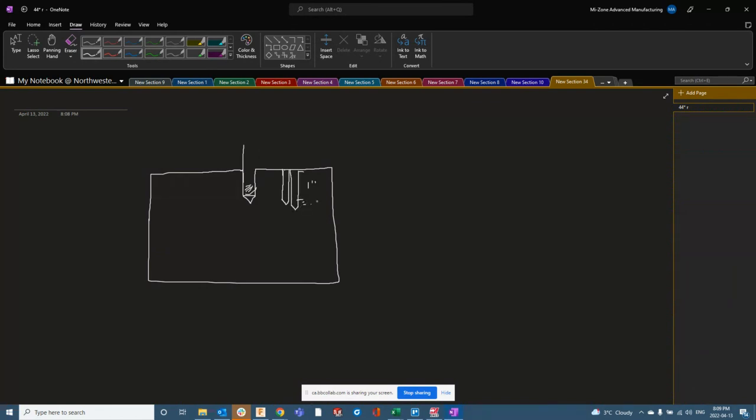So I said add 50 thou. So your drill depth in this case would be 1.05, but you have to make sure to add your tip comp. And then there's no breakthrough because it's a blind hole, right? So now the distance between here and here is 1.05, and that allows us, when we come with the tap,